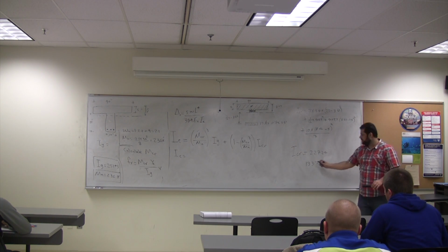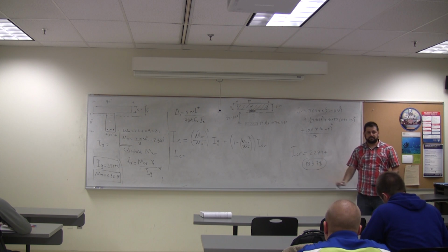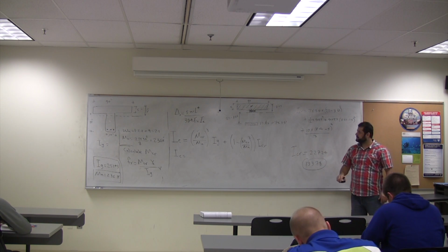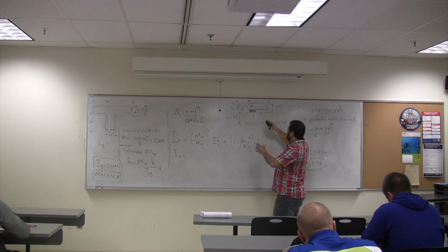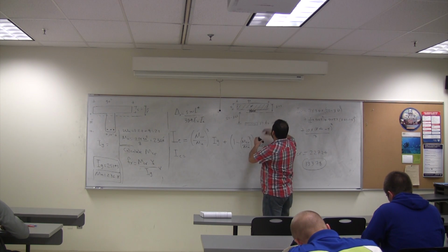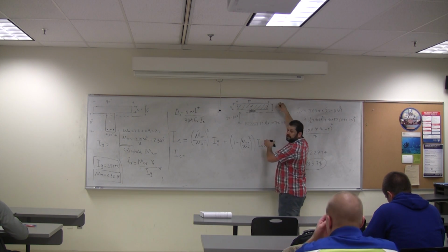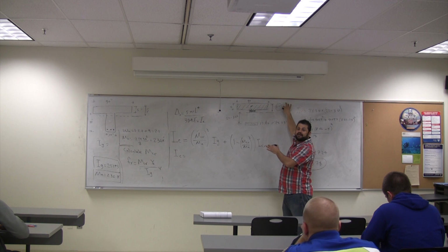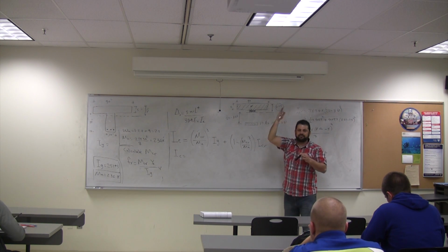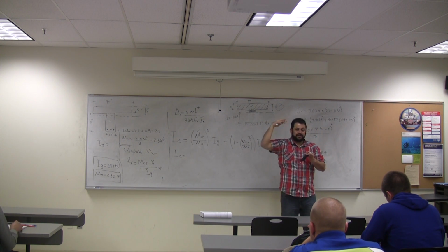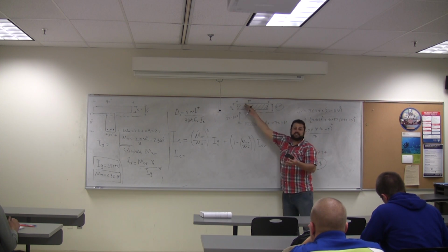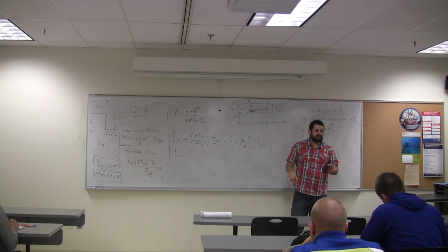Again, you know how we get to this number here? Since our KD is greater than the flange, we calculate this number to be greater than the flange, so this number now is not a real number. You remember the value of A? This number assumes this cross section is all rectangular, but it is not.